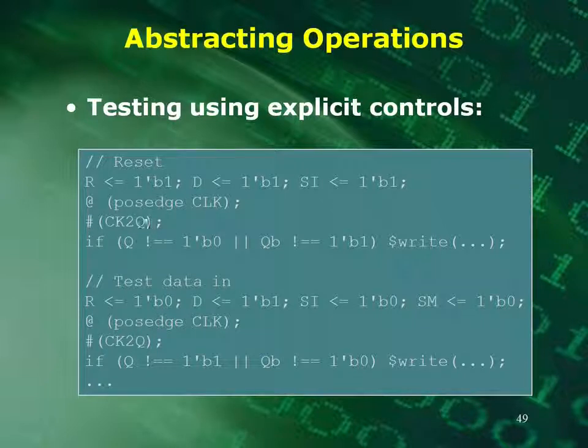And then here I've said delay, and I'm delaying somewhere I've defined this, our clock to Q, because remember when you're clocking a flip-flop, there's a propagation delay from the time that you clock it, the clock edge going high, to the actual output being there. So I want to wait until I know that the output is going to be there based upon the input.